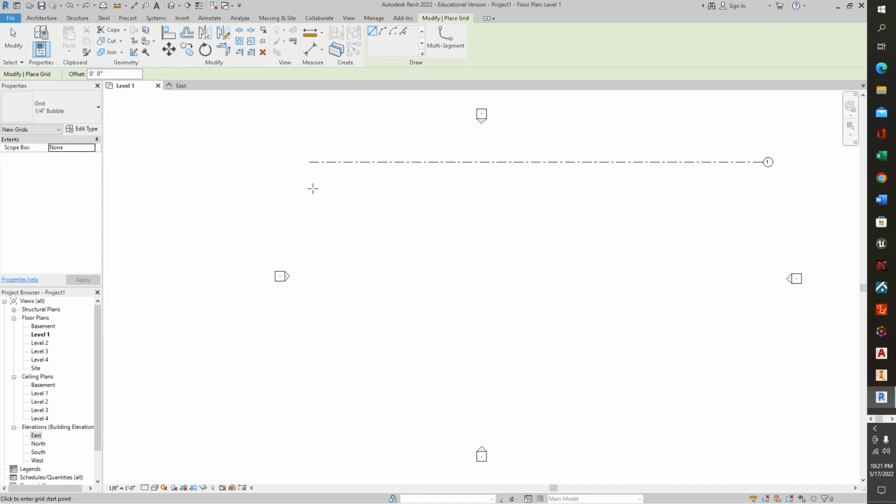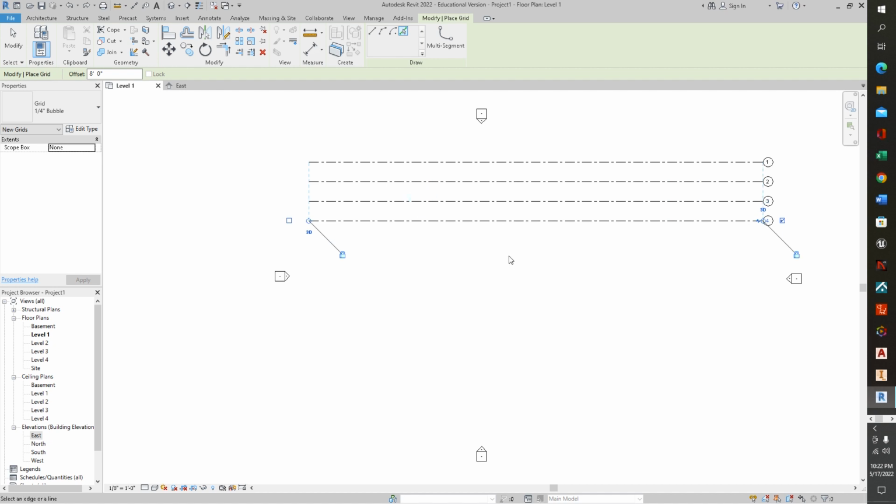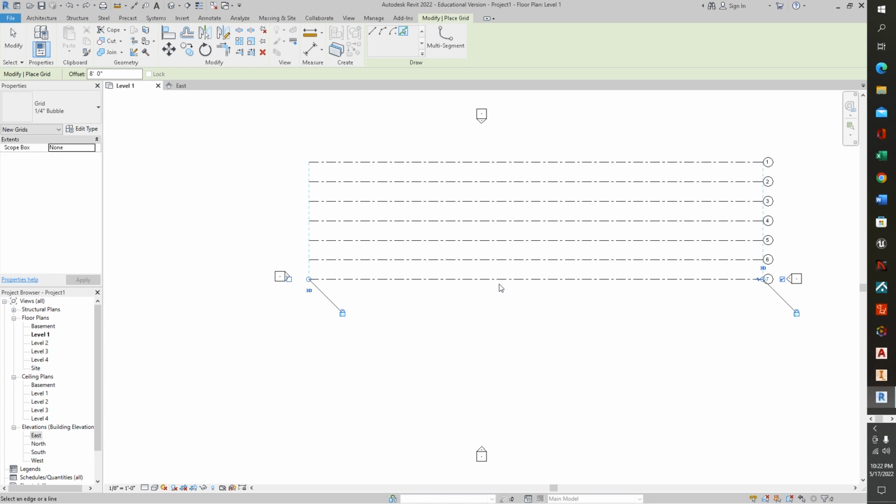We're going to escape out of that, so we're going to go up here and pick lines in our ribbon at the draw tools box here, pick lines, and as I said before, it's a commercial building. Maybe we'll put our spacing at 8 feet. So for that, I mean, this could get quite out of hand and look quite busy, because a house isn't really going to be that big a thing, but we'll keep clicking these down and make them 8-foot increments. Sure, why not?